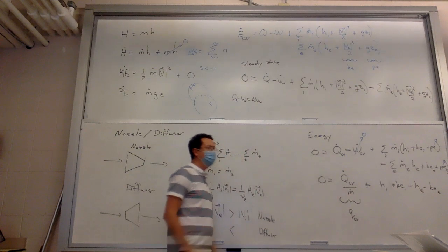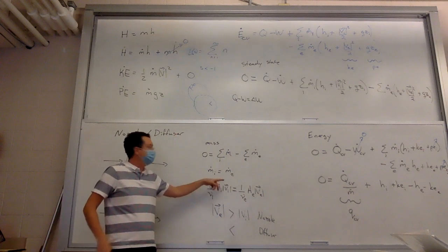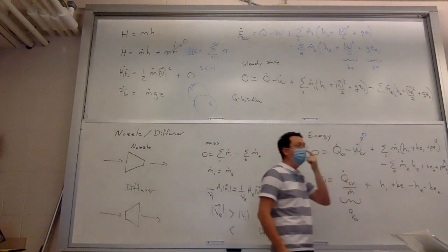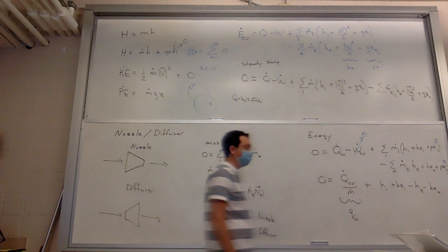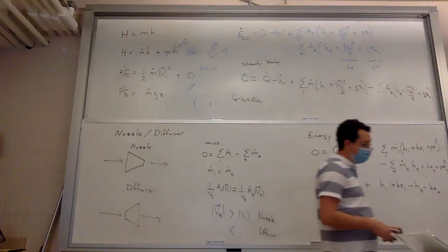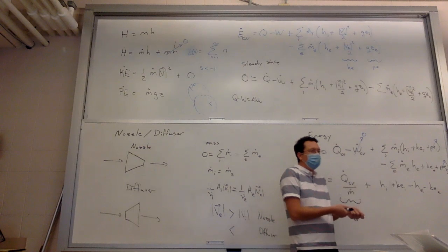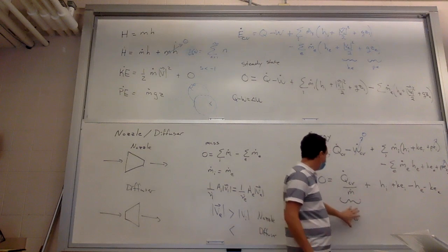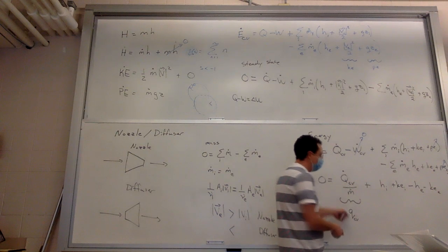So if I write it that way, all the time dependence goes away. Really, that's always going to happen for us. All of the real time dependence is just in this m dot, which is just some overall factor. Everything else is just going to move. The interesting stuff is all just in the intensive things, which are constants. Okay, so we get that. Now, for many situations, the heat is basically zero. Like when water goes through a garden hose, there's not really significant heat radiating through the nozzle. So for many situations, you set this to zero. So usually this is small.